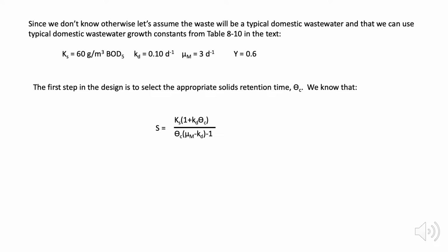So the first step in the design of a treatment process like this is to determine what's the appropriate solids retention time, or mean cell residence time. We'll use the symbol theta C to represent that. And we developed this equation in class that says the effluent concentration from this treatment process would be equal to the equation that you see here.